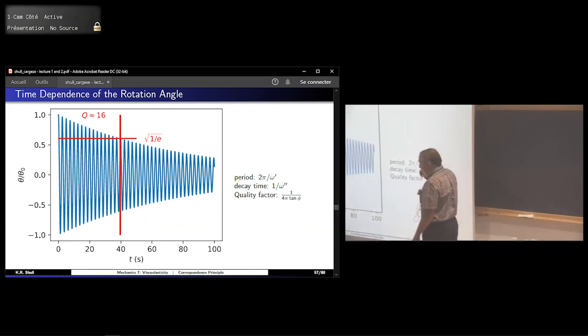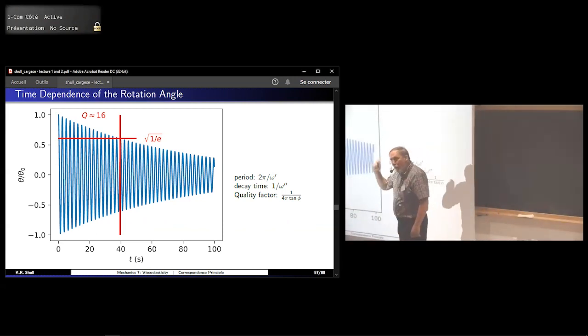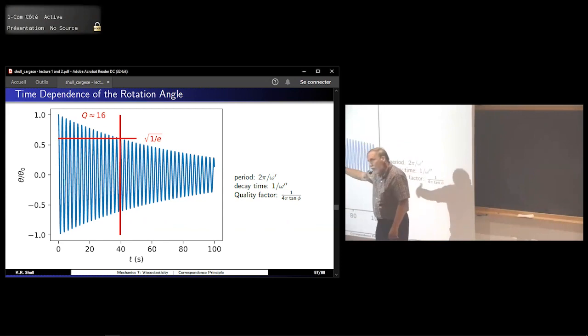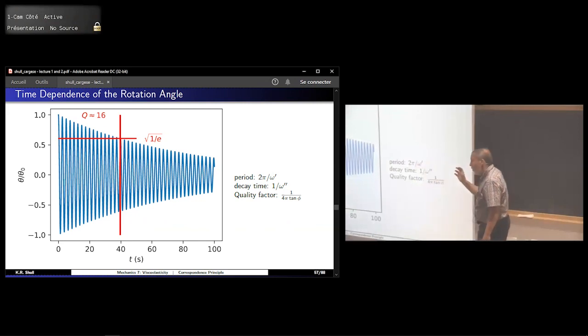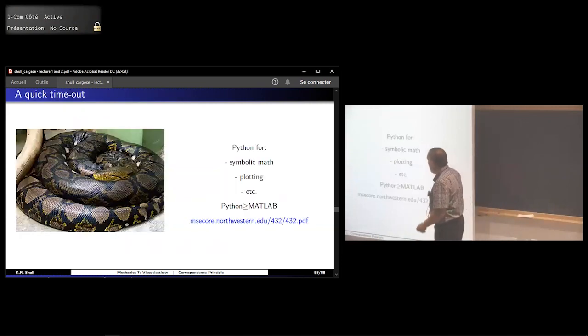So if you think about a tuning fork or a bell or something like that, where you hear a sound at a few thousand hertz, and you hear the ring tone last for a few seconds maybe, that's going to be a quality factor in the thousands. So this is a pretty crummy one, but it's about as good as you can do with a glassy polymer system because the phase angle is pretty low. Okay. Yep.